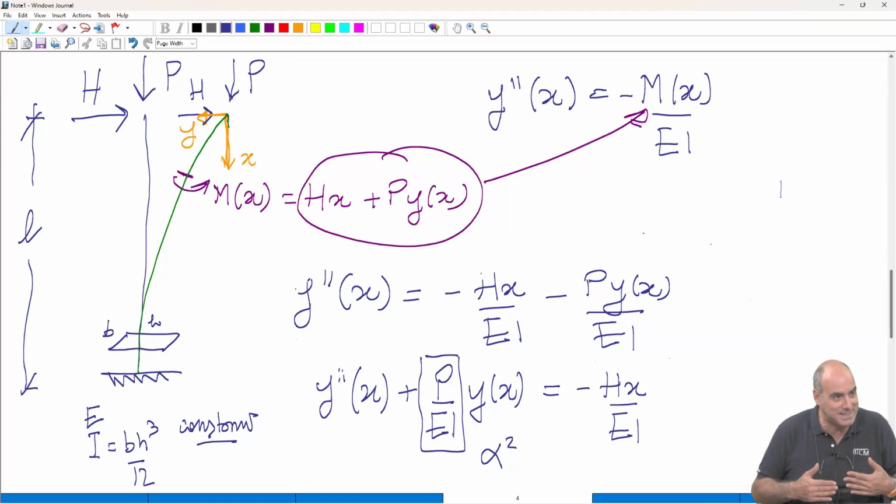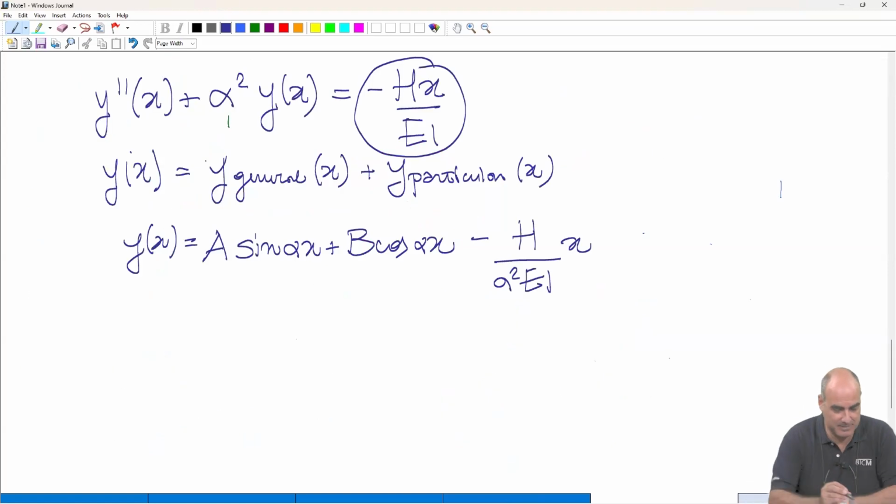So I always see it fixed at the top edge. What I see moving is the bottom edge. So the boundary condition has to be written in the reference system. Then it's true that the rotation at the bottom is 0. So it's a really important choice.